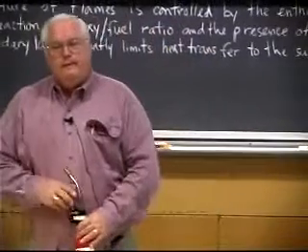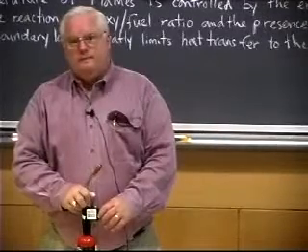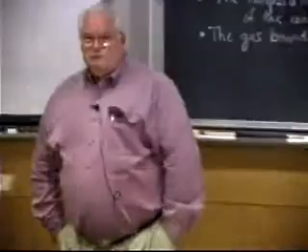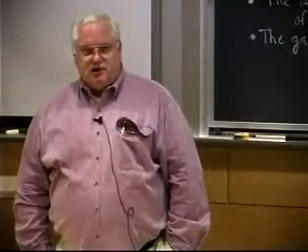Yep. Lean flame is one. When you say lean, are we oxygen lean or fuel lean? Your fuel lean. Usually, when you talk about lean, you're talking about not enough fuel. Rich is you're burning excess fuel, and lean you're burning excess air.